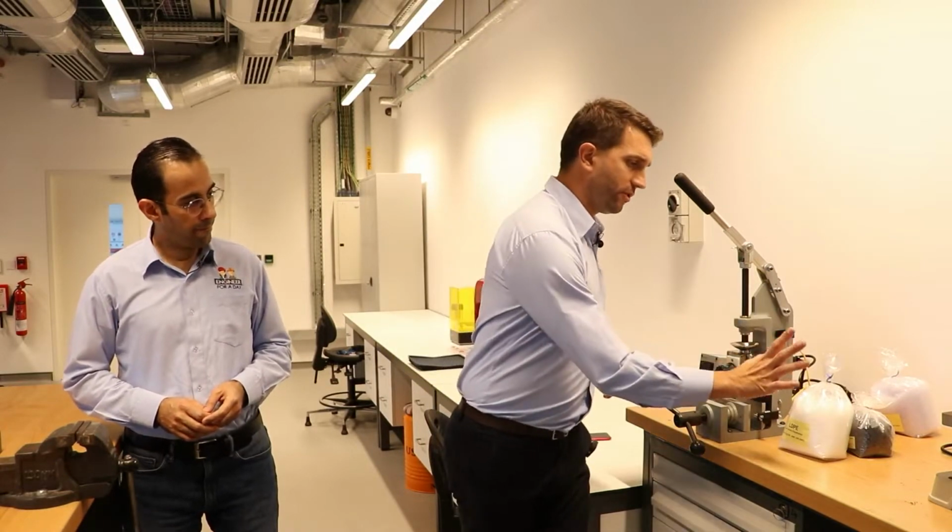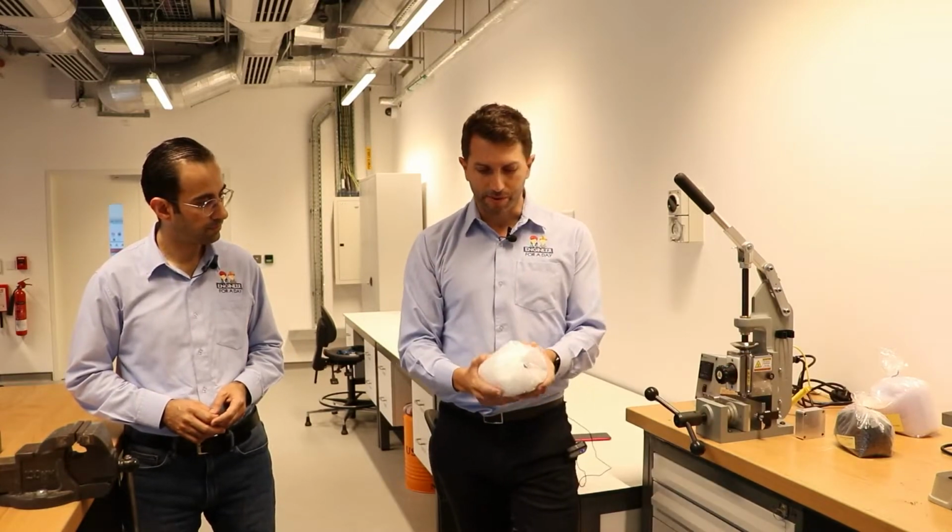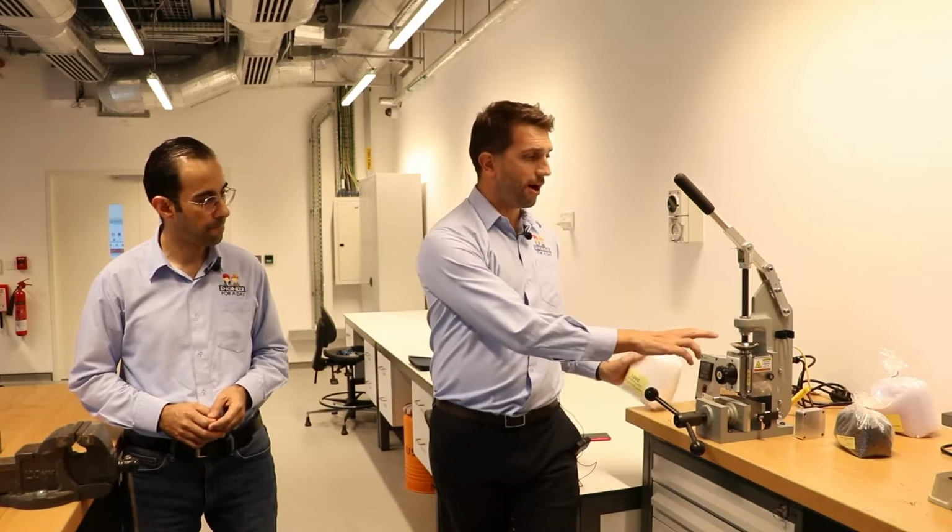I'll explain what that is first before we then maybe give some examples. What we do is we take, well, some beads of plastic. This is the raw material. And we put it into a hopper in here. Now this heats it up and essentially melts it at about, well, in excess of 200 degrees Celsius. So you can imagine inside this hopper, you have this molten plastic.